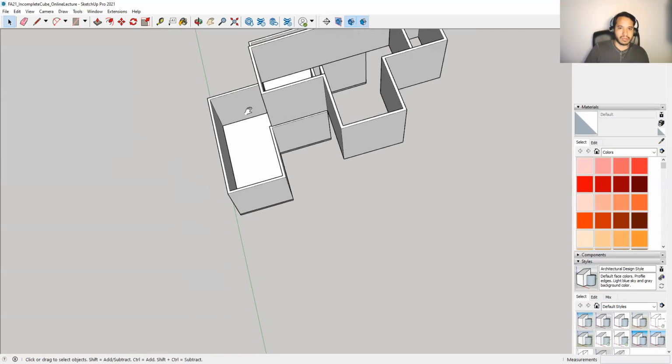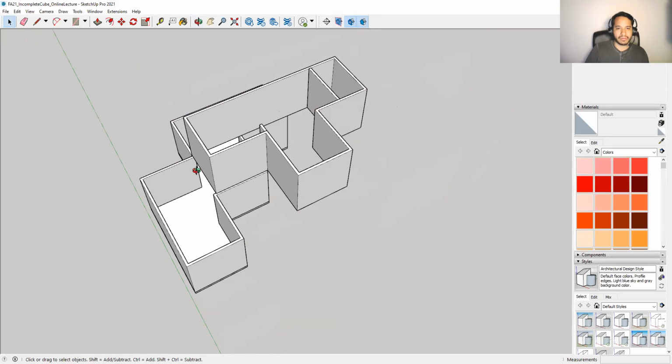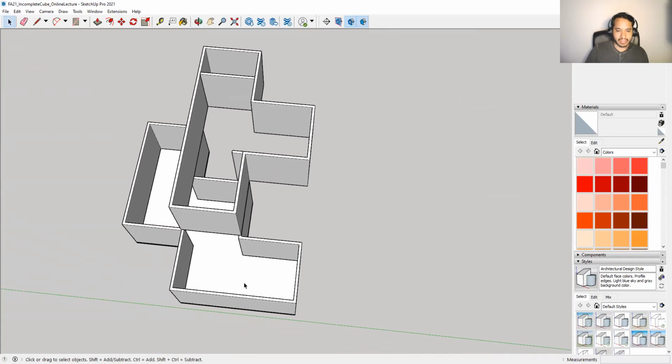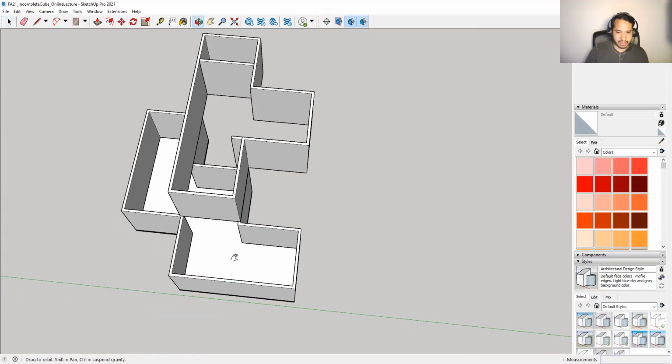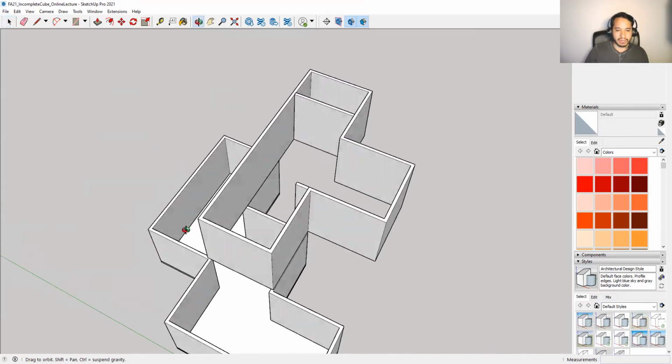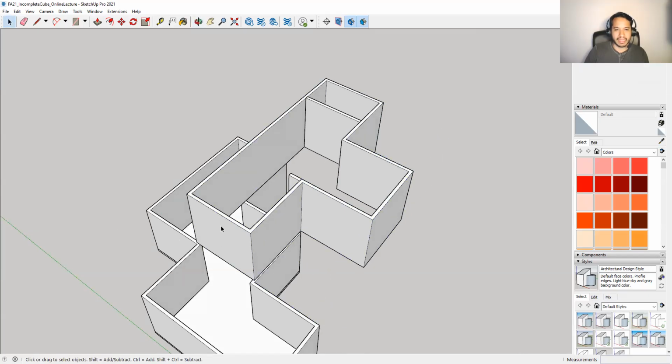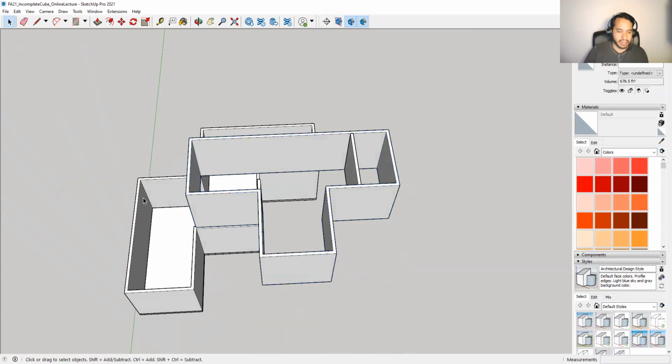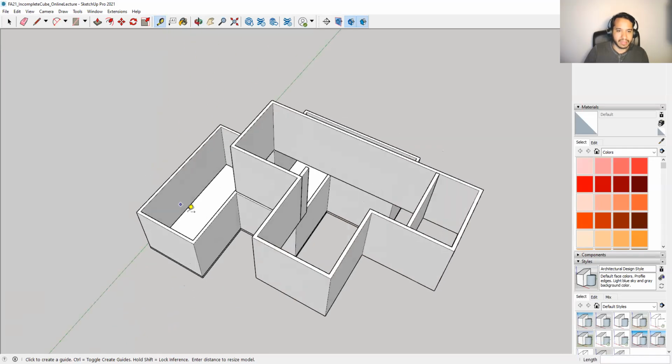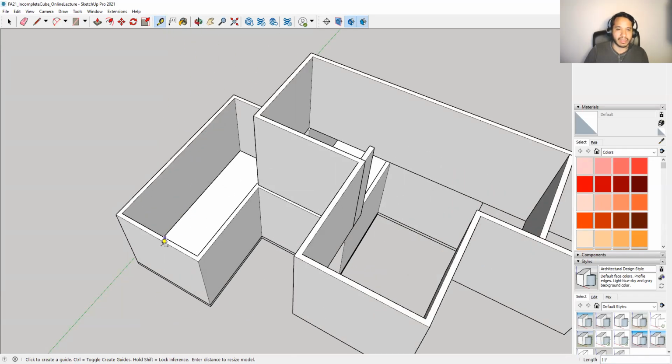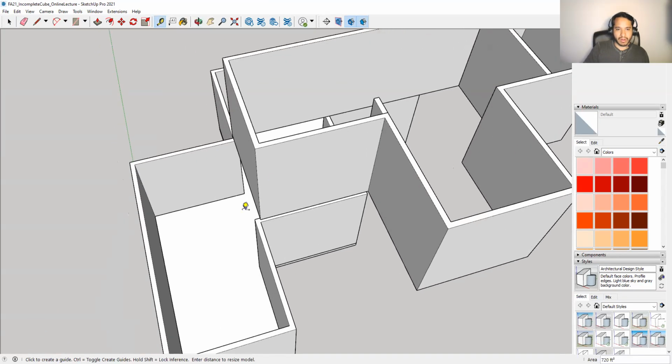Obviously, there's only a few walls that actually run 18 feet, 6 inches. Okay. But none of them actually run in such a way that it allows me to enter this space, right? Over here, this wall, for example, I think it's 23 feet. I have enough space to have a straight run staircase that goes straight along that wall. But when I go up to the second floor, I'm going out to nothing. So that means that what I want to do is be able to go in. So when I go up, I'm actually going into a space.